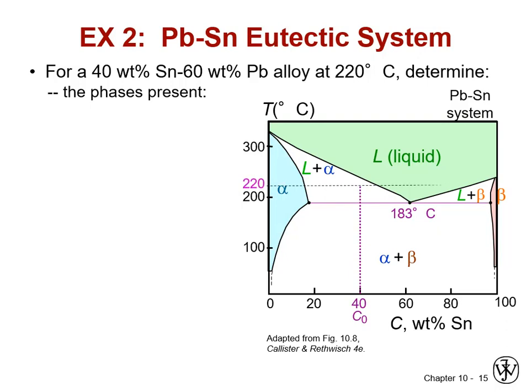So in this case, now we're going to look at what would happen at higher temperatures. What if we took that same alloy and heated it up? So now we are in a two-phase region, alpha plus liquid. So we look at where our black dot is and go up. Okay, there's no more beta. It's gone. So we consumed all the beta and turned it into other things, mostly liquid in this case.